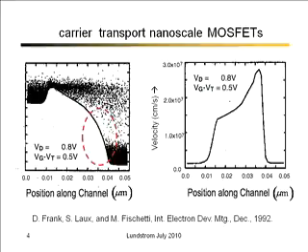Now, if you've seen transistors before and taken courses, one of the things that you'll remember is that the slope of the energy band diagram is the electric field, and the electric field is very strong near the drain because the slope is very steep. And one of the things that you learn in basic introductory semiconductor courses is something called velocity saturation.